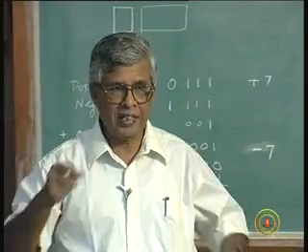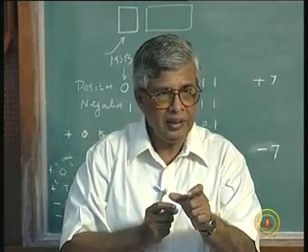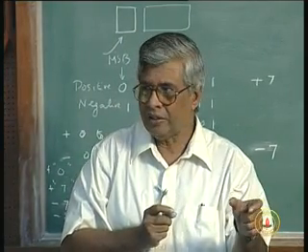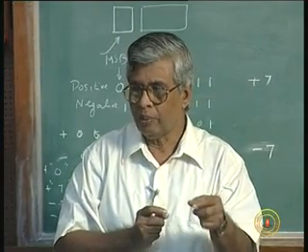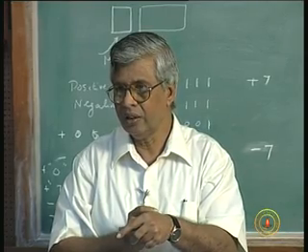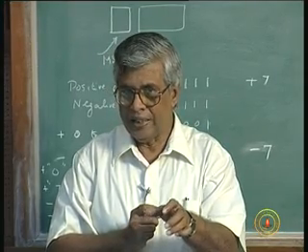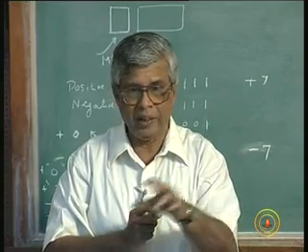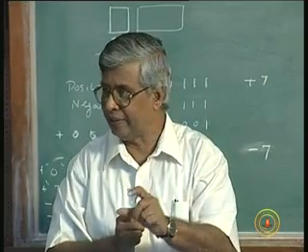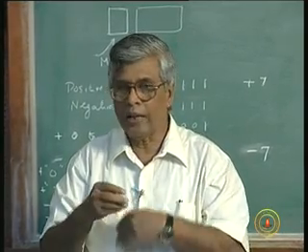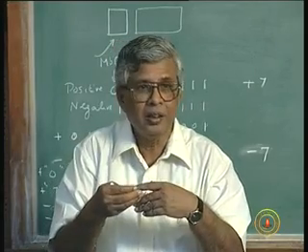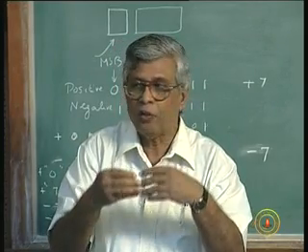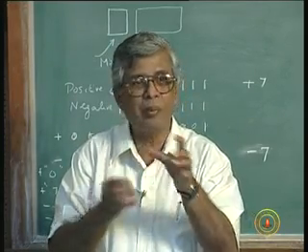So, I have a range of numbers, I can represent only 0 to 7 or minus 1 to minus 8, which means I can only represent the magnitude of these numbers using 3 bits. So, all the arithmetic operations should also result, the sum or the difference should always be less than 3 bits in magnitude.